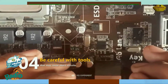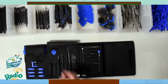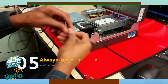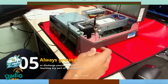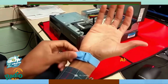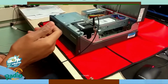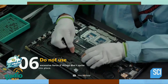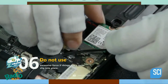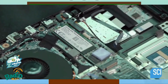Number 4. Be careful with tools that may cause short circuits. It's better to buy good quality tools with anti-static features. Number 5. Always ground or discharge yourself before touching any parts of the computer. Pro tip: touch the power supply for at least 10 seconds and you'll be fine. Number 6. Do not use excessive force if things don't quite slip into place. Always look for the markings.